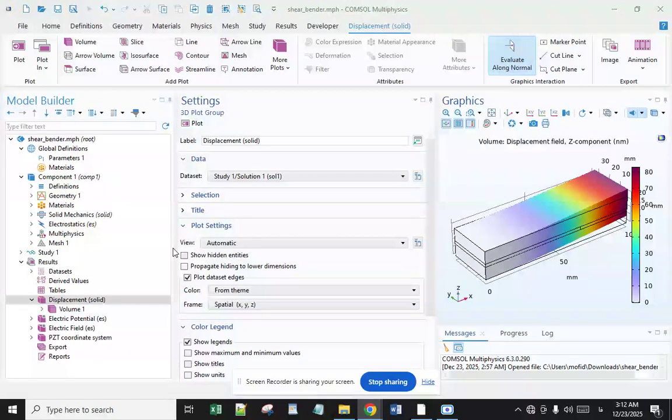This is a great advantage for the shear actuation mechanism since, contrary to the extension one, its performance is preserved for stiffer structures. This figure in this simulation also shows that there is an optimal stiffness ratio range for which the shear actuation mechanism is always better than the extension one. This is the case for piezoelectric PZT5H and a stiffer material.